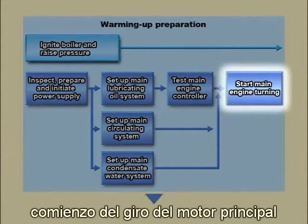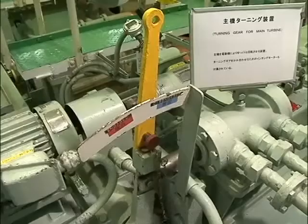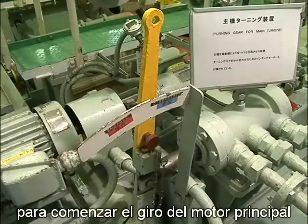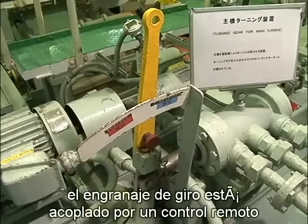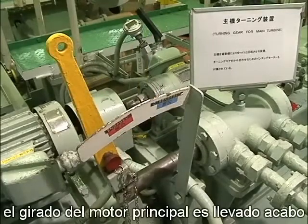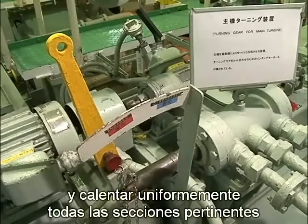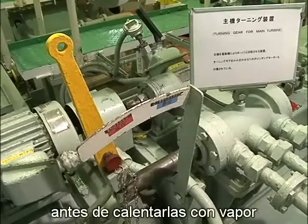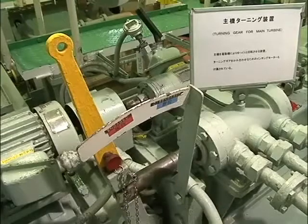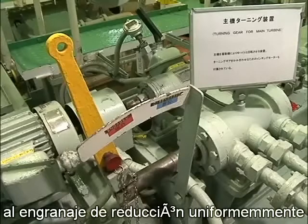Start main engine turning. To start the main engine turning, the turning gear is engaged via remote control from the control room. Main engine turning is carried out to rotate the rotors and uniformly warm up all pertinent sections prior to heating with steam. It also helps to supply lubricating oil to the reduction gear uniformly.